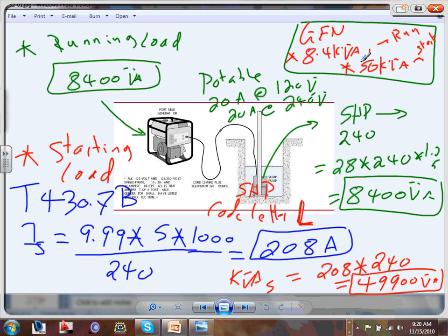Just like a time on delay, the standard. Time on delay on the generator, yeah, you delay them. You delay the transfer switches, you stagger them. The first load, the first 500, will start at 10 seconds, then 20 seconds, 30 seconds, 40 seconds, 50 seconds, and so forth. Any questions, guys, about reducing the inrush when you size a generator?